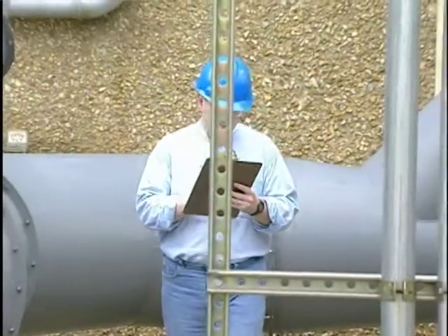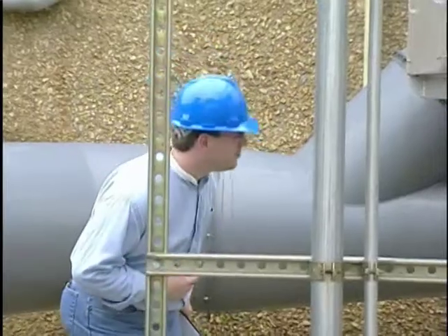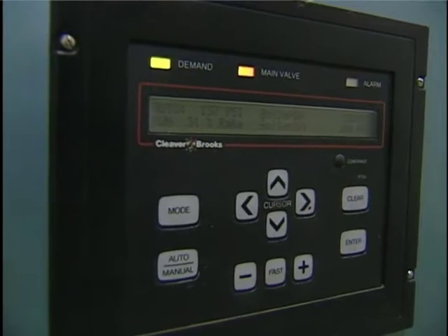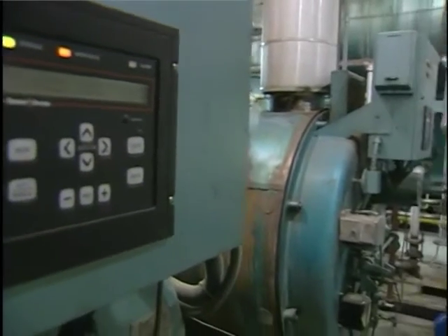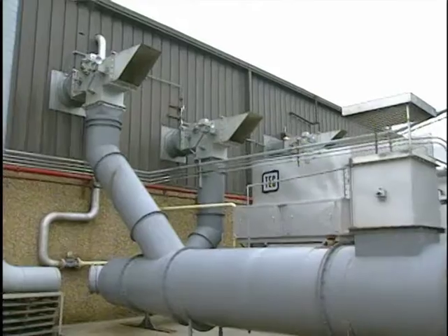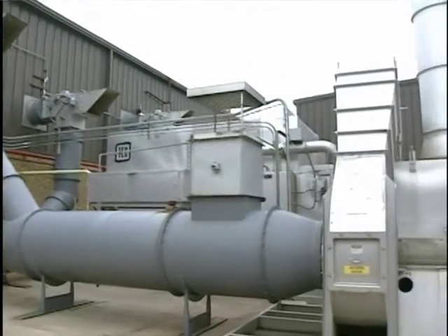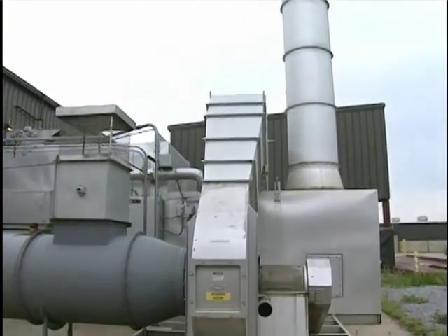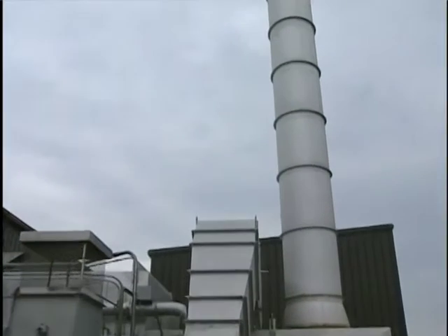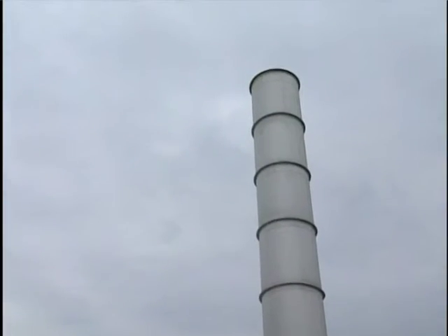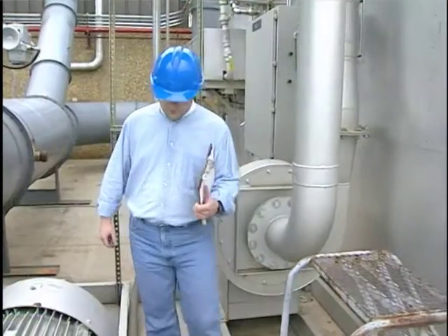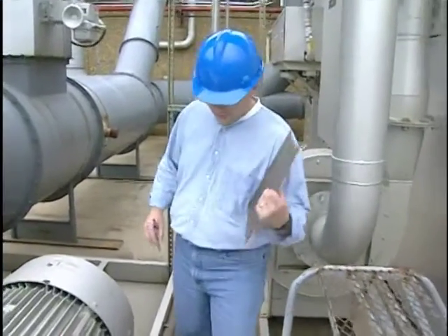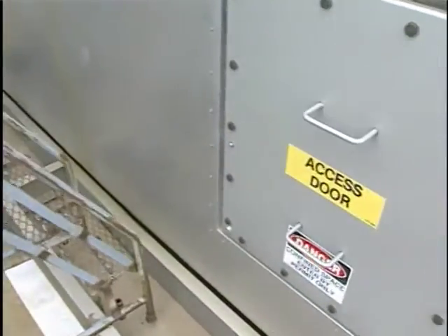There are some limitations in the use of a process heater or boiler as an incinerator. The boiler must operate within about 40 to 100% of the design load in order to have the necessary temperatures for organic vapor destruction. The waste gas stream should be only a small portion of the total gas flow through the unit. If the volume of additional gas is large, maximum recommended velocities through the unit would be exceeded, potentially lowering the destruction efficiency of the system. Finally, there should be nothing in the waste gas stream or its combustion products that would present a corrosion problem or cause deposits on heat transfer surfaces.